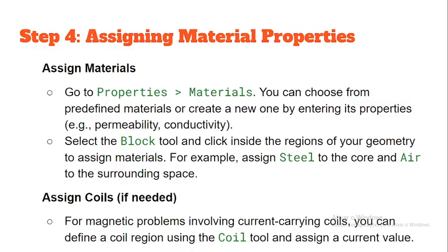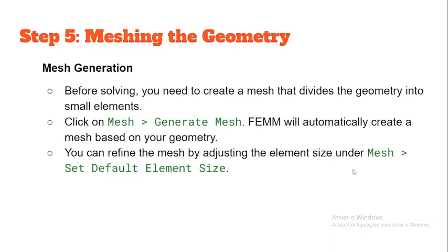Assigning coils, if needed. For magnetic problems involving current-carrying coils, you can define a coil region using the Coil tool and assign a current value.